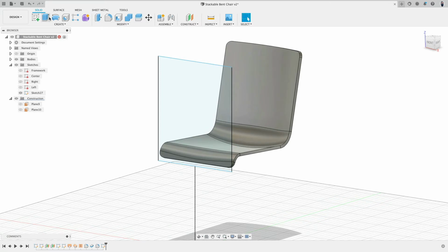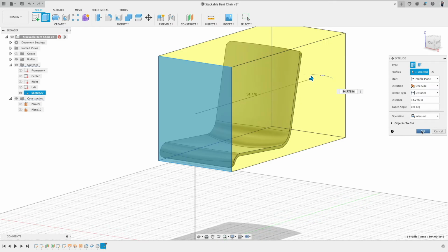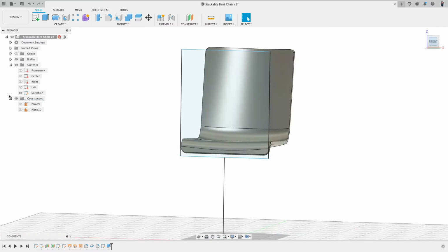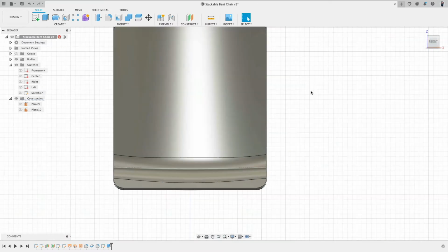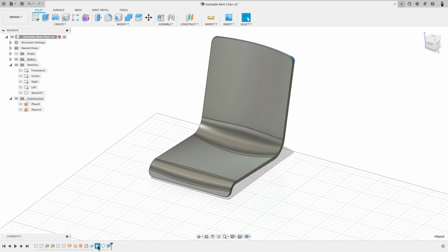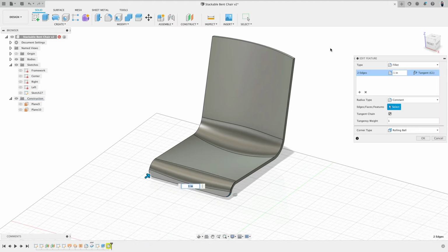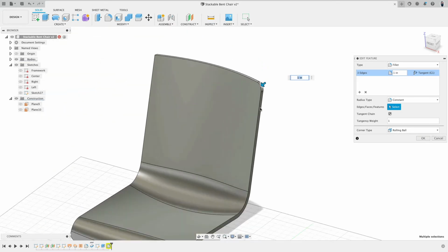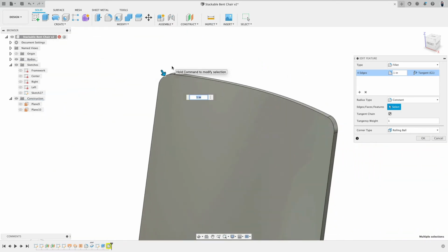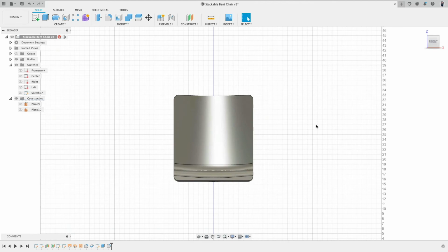And then I will go to extrude and extrude this one through there and then switch the command to intersect. So I keep just what's in there. And then when I take a look from here, yeah, that's nice and clean. The fillet here is garbage. And well, that's because I cut through the fillet, which means this has to go after the extrude. Then there's a warning because the command actually forgot which edge to round. So go back, hold the Apple or Control key and clean this up. Very good. Yeah, that looks really nice.